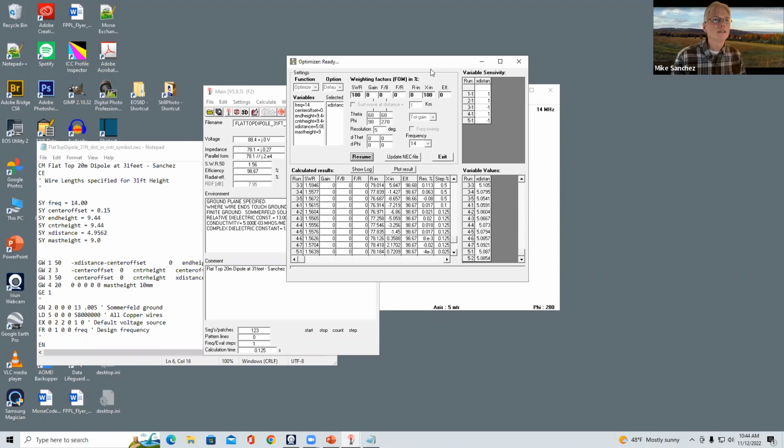I will say it doesn't affect anything. I know from running the dipole from our last assignment that the Smith chart plot tends down towards the infinity side on both sides of the axis, so that x equals 0 would be the lowest SWR in this case, even though it's 72, 73 ohms.